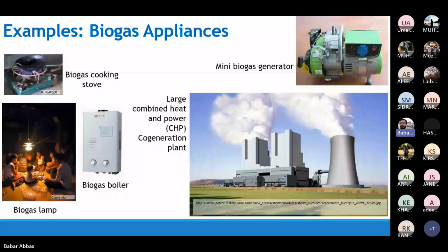How pH can impact the performance of the bacteria. Total solids and moisture should also be taken into the account. Wet digestion takes place with less than 20% total solids, and dry digestion takes place with a higher quantity of the total solids.